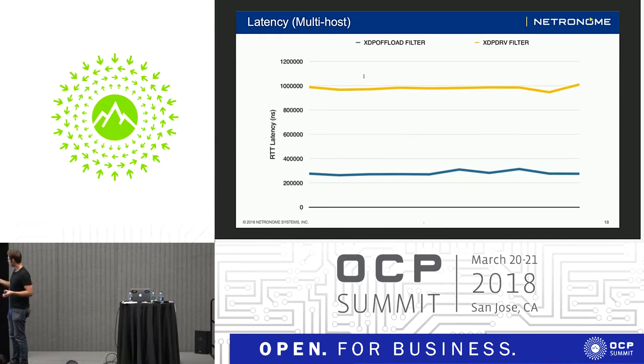So this is when we're simply comparing running it in the driver and running it offloaded. You can see in this case, when you've got a PCI link under stress, then you end up with a very, very significant latency reduction. And at this point, the variance we were seeing earlier, you'll see, oh look, it looks much more smooth now. The reason for this, I believe, is that the numbers here are so much bigger that the variance doesn't show up as much. So that was really all I wanted to go through today.